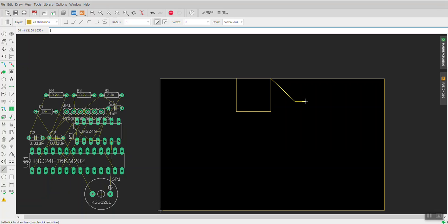At this point, I'm finished with that piece, but it's not really where I wanted it to be. If I look at my requirements, I wanted this to begin 1.5 inches from the edge. If I look at where this is located right now, and again, notice it's the first number that's giving me the horizontal dimension over here, it looks like I'm at 1.1 inches, so I need to move the whole thing over.